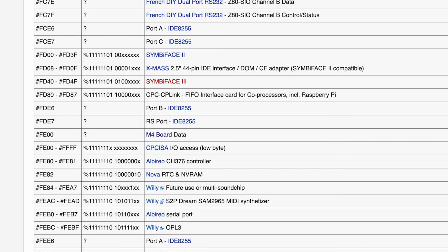When you look down the list, you see that a lot of entries are taken, and what's worse, there are some extensions that claim a whole range of bytes to themselves. That might have been okay for the original board, but now, given how congested that table is and how easy it is to implement the bit logic on a CPLD, there is simply no excuse for a modern device to only do partial address decoding. So if you're making a device today, please confirm that there's room in that table and that you're only active when all the bits you've selected are active and no other time. Otherwise, you'll be running into constant conflict with other hardware, and I've actually seen several devices doing that.